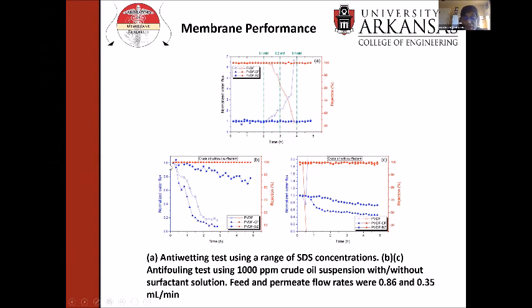For the PVDF and the PVDF-CF membranes, you see the flux starts to decrease almost immediately and relatively rapidly. Soon the normalized flux is very, very low. It's almost zero. The PVDF-BZ membrane, which has a very strong hydration layer due to the presence of our graft and zwitterions, actually resists fouling or adsorption of oil. And you can see the flux does decrease, but much, much more slowly. So the productivity of this membrane is much better. We get much more water that we can produce, treated water.